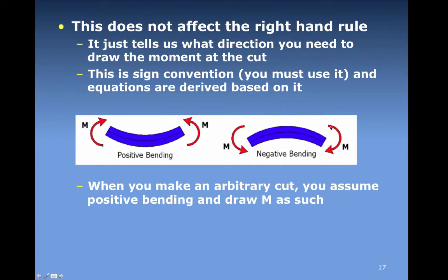In comparison, if we now have moments that are applied in the direction shown here, this creates a frown. So, briefly, positive moments create smiles, negative moments create frowns. Hopefully this is a trick that you'll remember again and again in looking at beam bending.